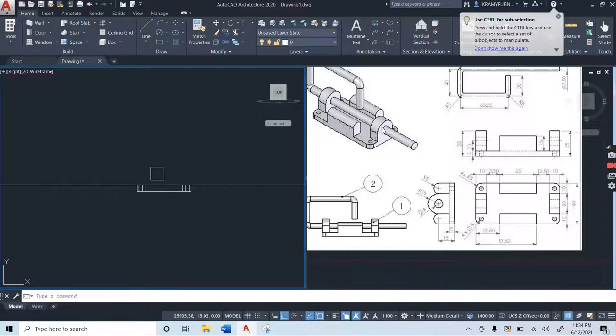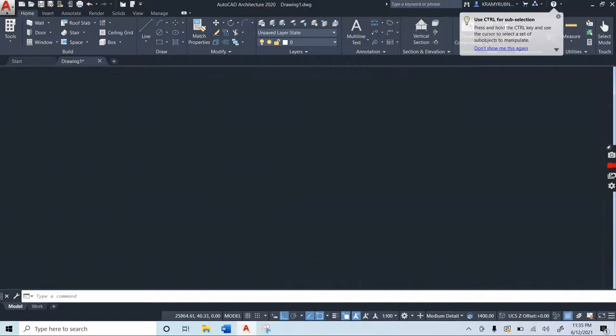Let us now make our square that we're going to be using to form this end plate. Now that is going to be rectangle again, connecting the center, pull out, and that rectangle is of dimensions 20 millimeters across and 10 millimeters in height. Enter. Let's click on screen for our rectangle to be populated.